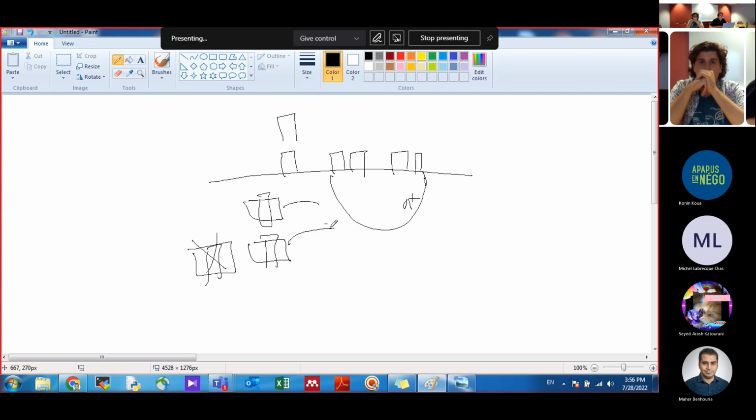This is the well. If you have one transistor, the N well, and then another transistor on the other side, they will both see the N well, even if they're not close, so they won't be as well matched, but they will both see the N well. Yeah, they both see that thing.